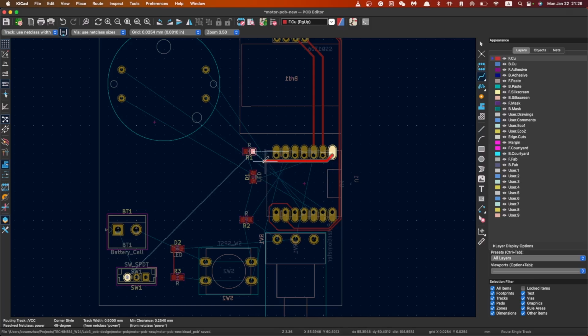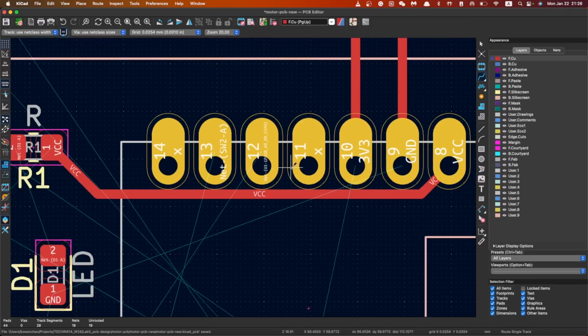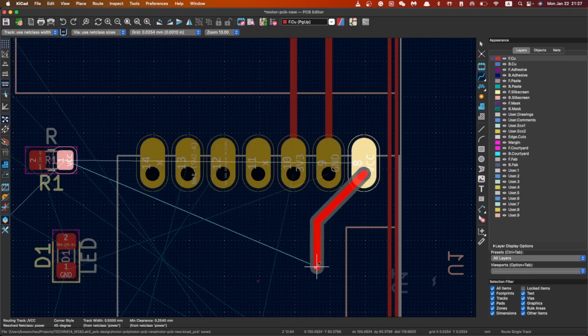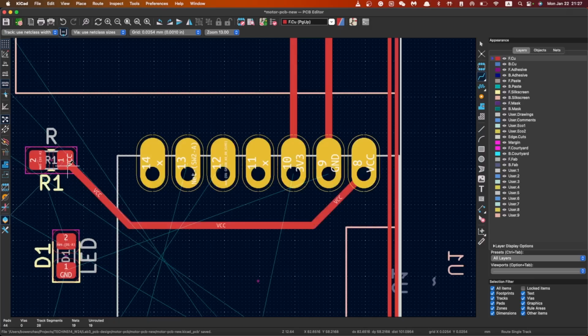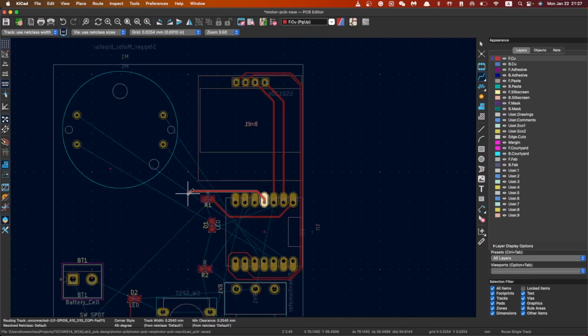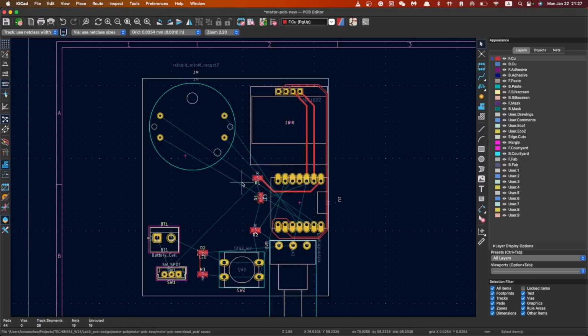I really don't like this style of routing because they're being too close. You know, you are going to hand solder these things all together in the last step. So I highly not recommend putting all these things so tight, right? Don't make this more difficult, don't add difficulty for yourself. It is not good to do so. Okay. So if we do this, this part will be totally blocked. If we do this, it's the same. Okay.